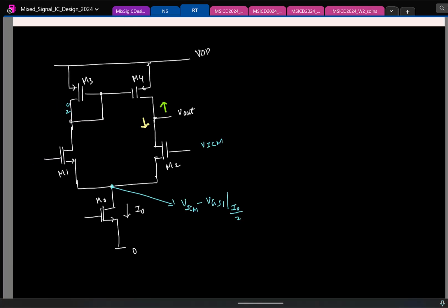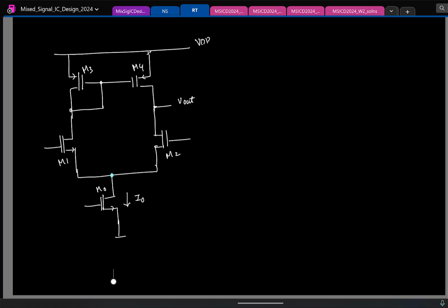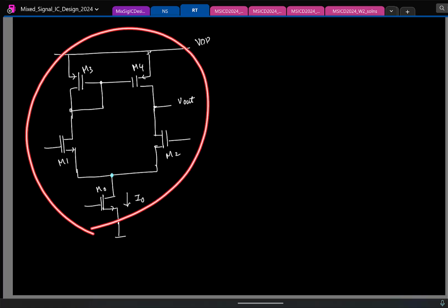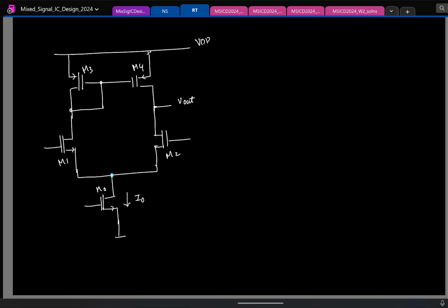So this is the op amp or the OTA we have so far. Okay. And what is the small signal gain, the differential mode gain? If I label the transistors, what will be the small signal gain? Differential mode. GM of which transistor? Yeah, I have labeled the transistors, right? GM either 1 or 2, both are identical.